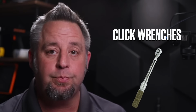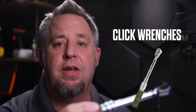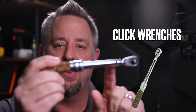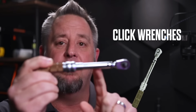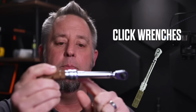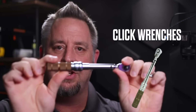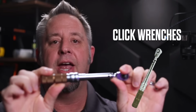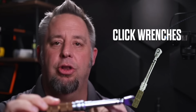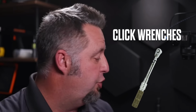Basically, inside of the cylinder tube, we have a fulcrum point where the end of the head meets the portion that is controlling the spring. When we get a certain amount of flex or torsion on that, we hear a little click, and that is what is called the pivot block hitting the inside of the tube of the wrench.